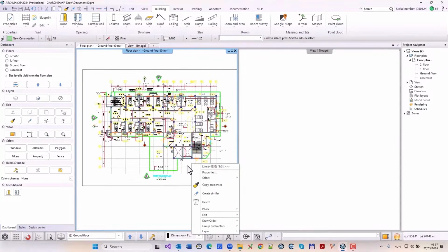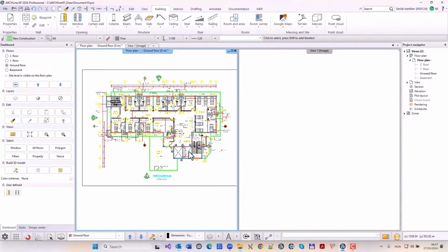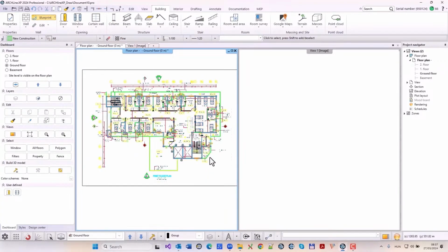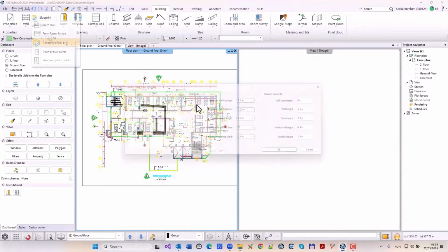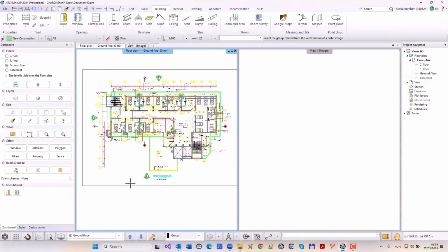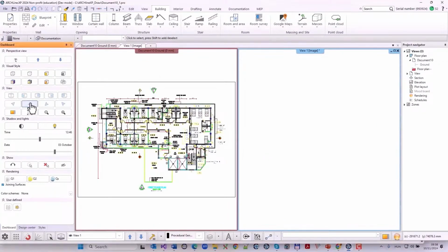The algorithm reviews the drawing and analyzes it, taking into account the specified wall and opening limits. During the review, it filters out unnecessary content and looks for those drawing elements that can be set with high certainty to represent walls, doors, and windows. These are transformed into real architectural elements in the next step.